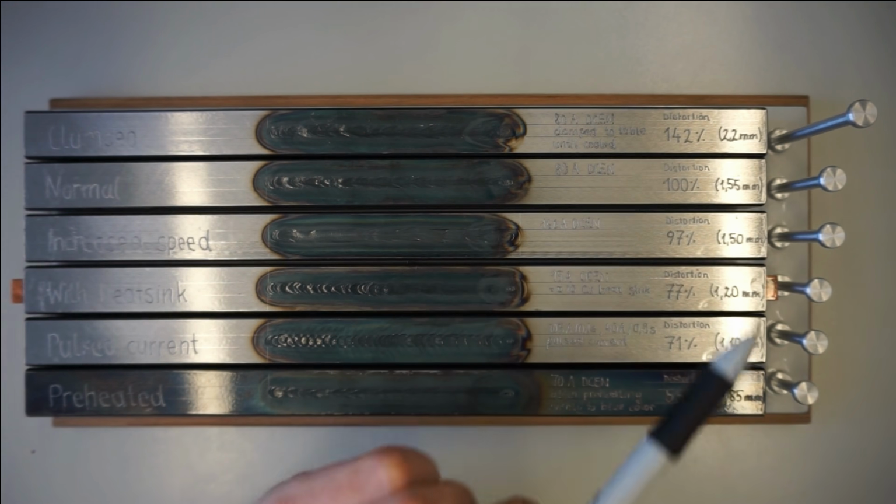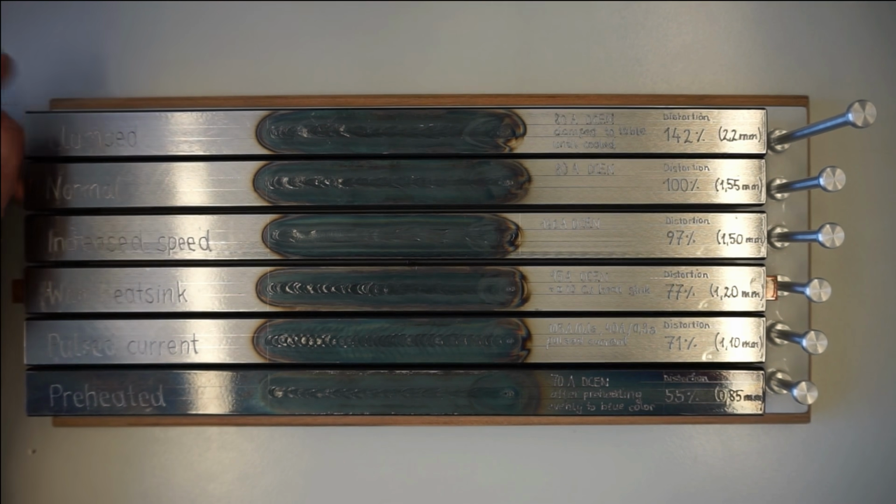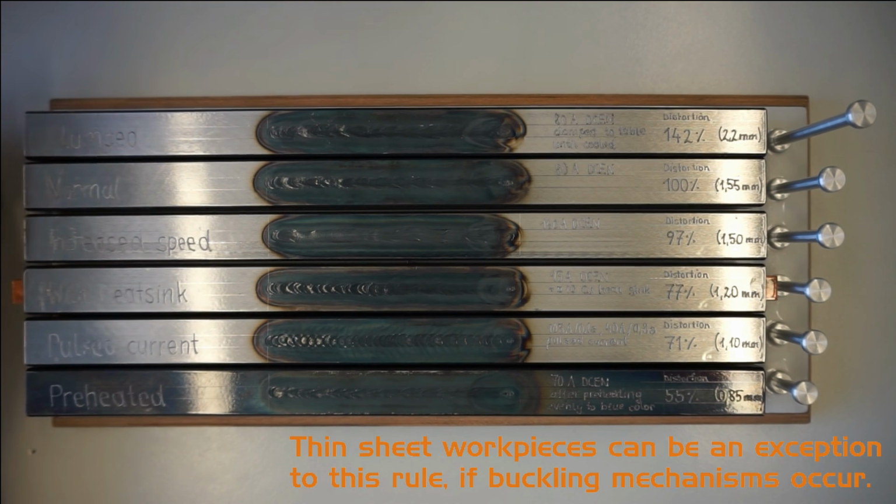This inversely confirms strategy number 2, which was increasing heated spot flexibility. This finding shows us that welding table, clamps and welding jigs are powerful tools for fit-up and tacking, but typically shouldn't be used during welding.